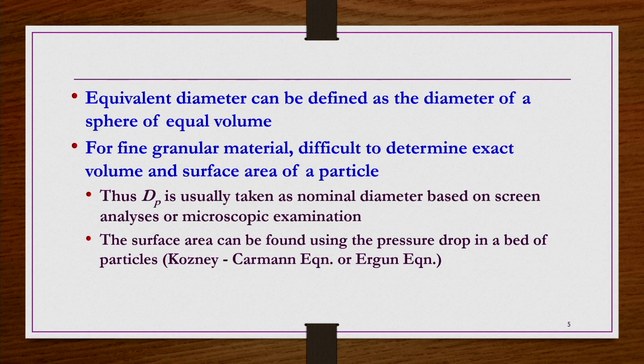Then these pressure drop values, along with the size of the particle and fluid properties, you substitute in the Kozeny-Carman equation, and from there you can find out the surface area of that particular unstructured material packing, right. We are going to do this in a subsequent lecture, probably in module 6.